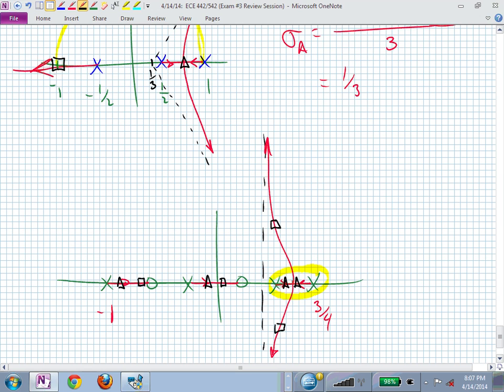And there is a limit to how far you can crank up K before that box goes outside the unit circle. And you could get a pretty good estimate of that if you know where that centroid is. Because you know the radial distance is 1, and you might know the real part, so now you can use your trigonometry. You know the hypotenuse, you know the horizontal, you could find the y. Now you know x and y. If you wanted to, you could plug that value in for x plus jy into your K expression, and that's your gain for stability. That makes sense?